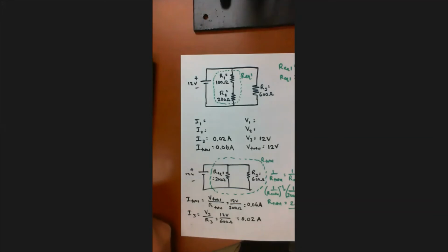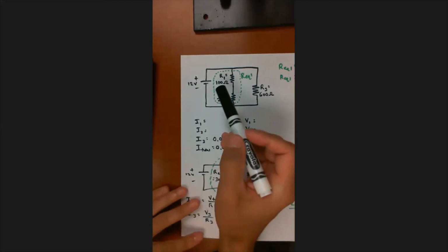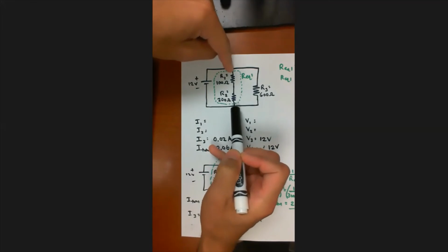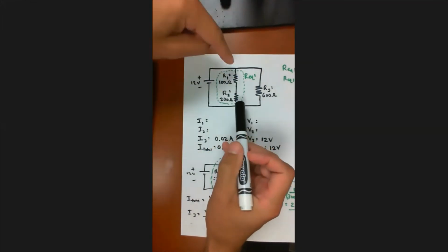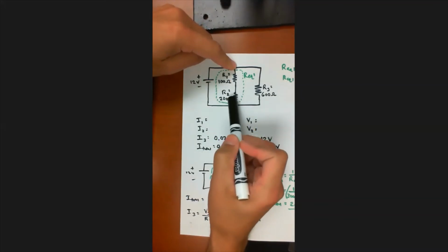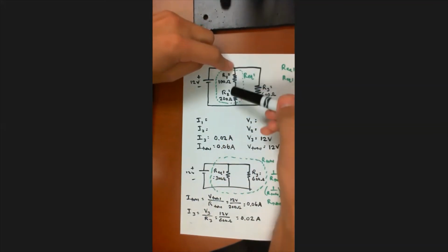All right. So there's several different ways that I can think to do this, but I think I'm going to use a concept that we just talked about, and that is the voltage divider, because it's applicable here, right? It's applicable because I know the values of these resistances, and I know the voltage drop across this branch. So these are in series, so I can use voltage divider, and I know these resistances, and I know the voltage drop from here to here.